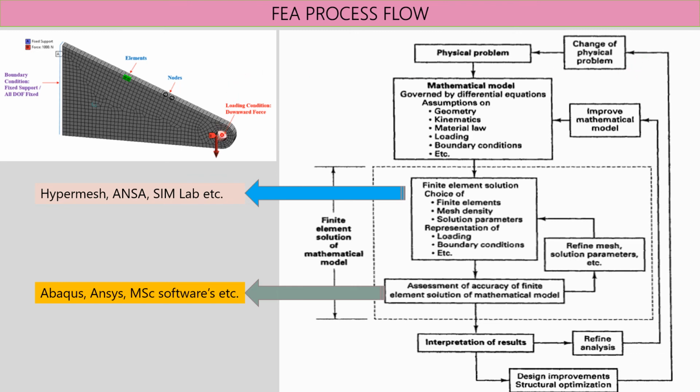For example, we are applying 10 kilonewton to this flange. If it can withstand even 20 kilonewton, then we go for structural optimization to make it suitable for only 10 kilonewton. This is the weight reduction capability we can achieve in our FEA analysis.